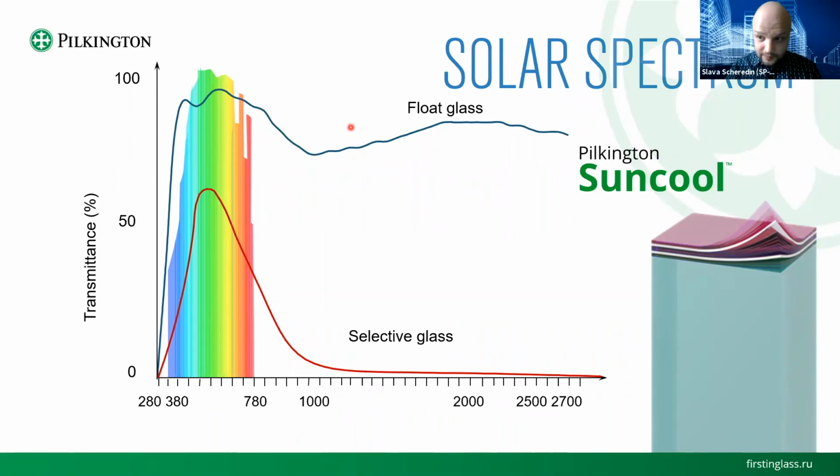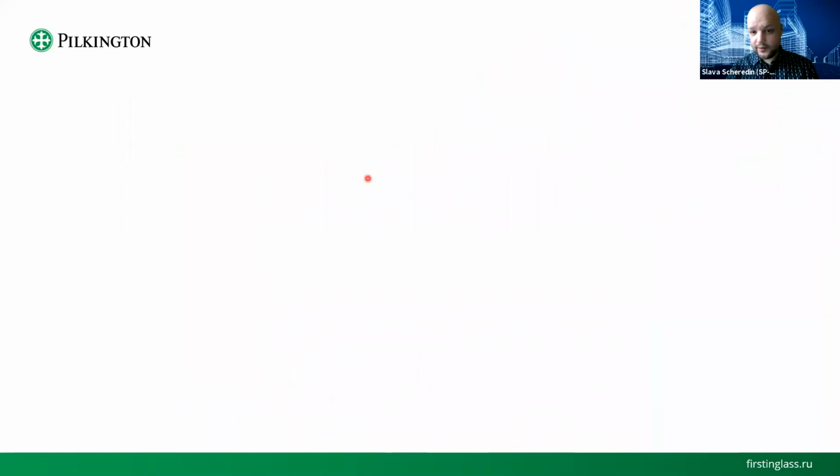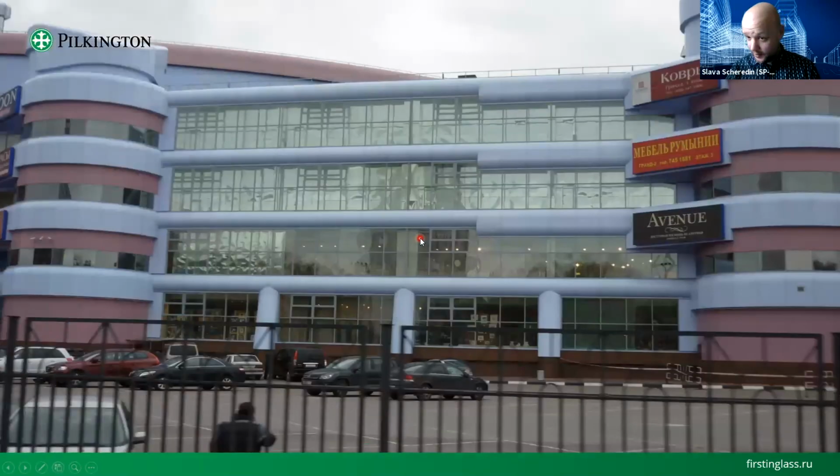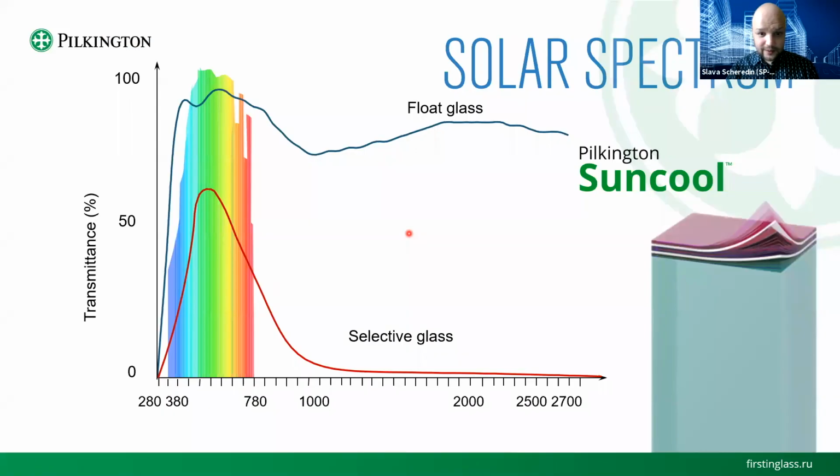For the best solar protection and for the best comfort, I advise to use special glass, soft-coated, solar control, and low E. On the Avilon, there is body tinted blue glass. Here, no solar protection whatsoever, clear float all the way.